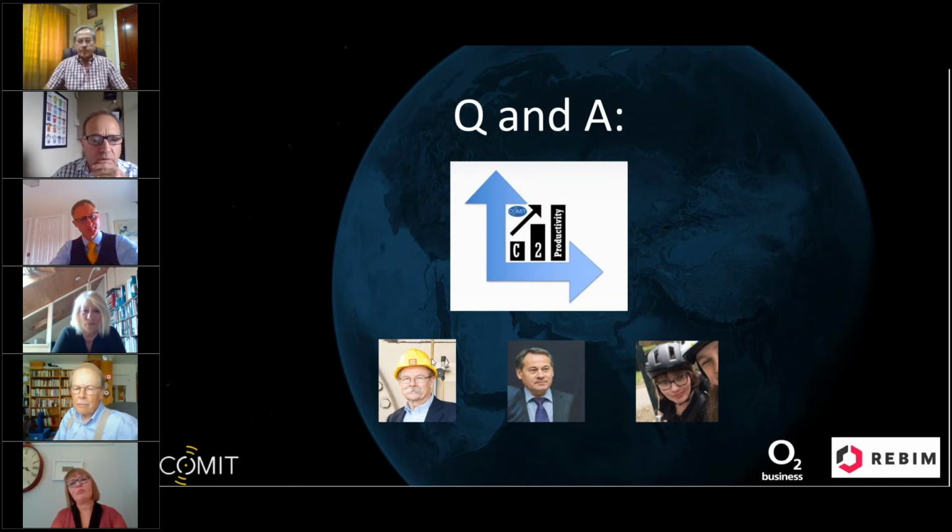So for example, if I'm a network utility operator and I say this is the location of this pipe, and I classify it as A, which means I know where it is to better than 40 centimeters, and somebody digs a meter away from that and actually hits the pipe because my data is incorrect, I, as the network operator, am responsible for paying for improving that information.